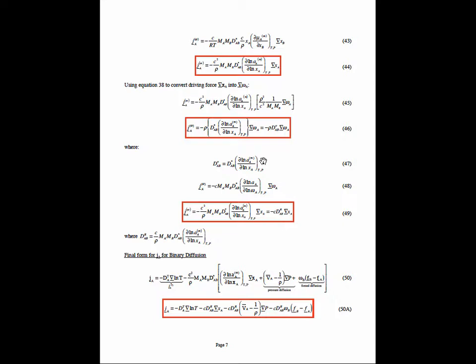And what this is showing is that the diffusion coefficients that we normally use in Fick's law, these so-called DAB0, or the binary diffusion coefficients, include a contribution from the thermodynamics of the system. That's not immediately apparent from writing Fick's law just as flux is minus the diffusion coefficient times the gradient in concentration. But if you go through a more rigorous view of this, you'll see that there are thermodynamic effects that show up in the diffusion coefficient. Those are not always important, but there are cases where these terms will essentially make the diffusion coefficients act strange if the thermodynamics of the system are somewhat unusual.